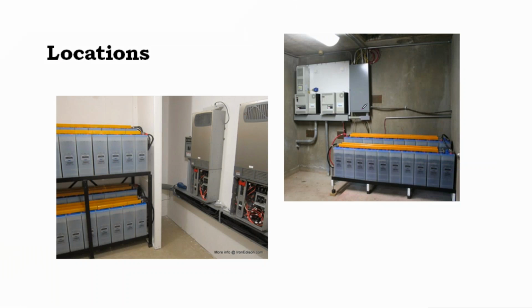Well, you can only have equipment sticking out no more than 6 inches from the front of this to the next piece of equipment. So, you might have your electric service panel here and your solar inverter here on the same wall, and that's fine as long as there's no more than 6 inches in depth difference between them.